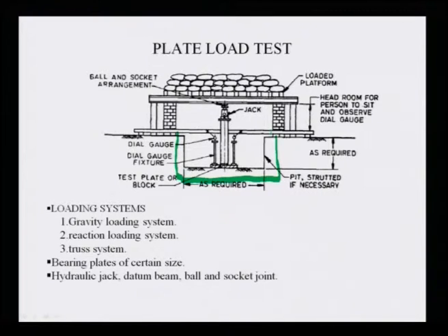Once the pit has been made, the plate is placed here, this is your plate. Then with this plate a reaction frame, a reaction beam, has been placed. Over the reaction beam a load platform has been made and load is also applied.